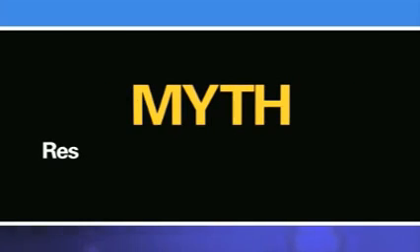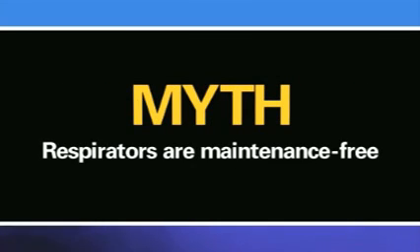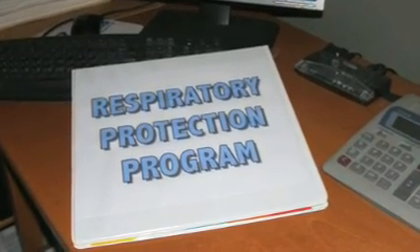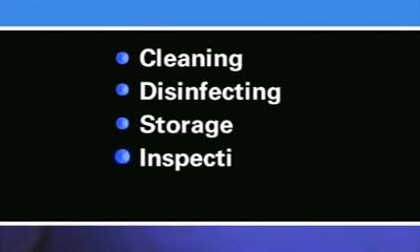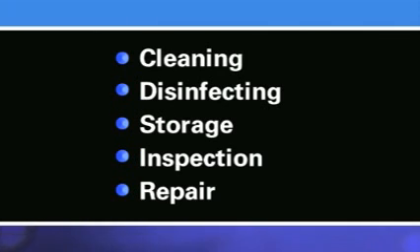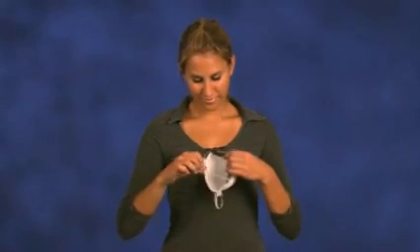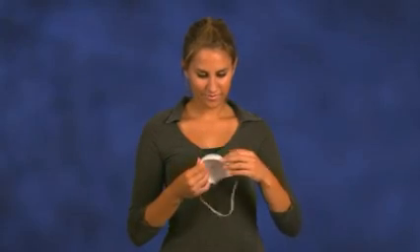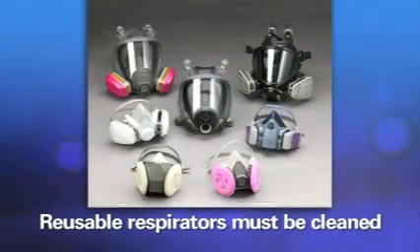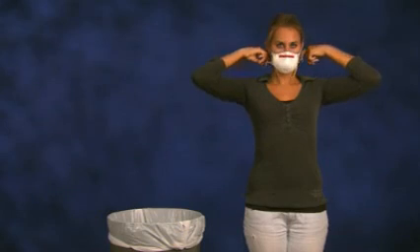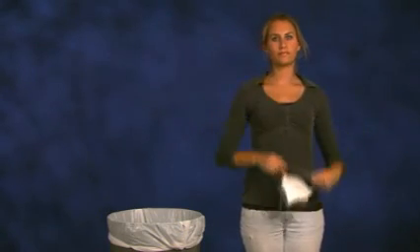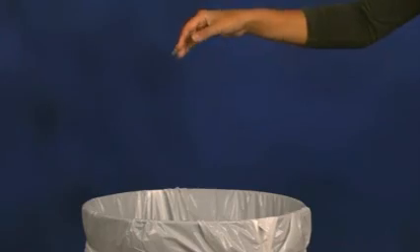Myth: respirators are maintenance-free. Your employer's respiratory protection program must provide for the cleaning, disinfecting, storage, inspection, and repair of each type of respirator used in your workplace. Remember, all respirators must be inspected for basic function prior to each use. Reusable respirators must be cleaned as often as necessary to prevent them from becoming unsanitary, while filtering facepiece respirators must be disposed of when they become soiled or no longer provide protection.